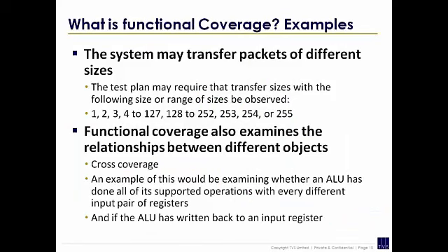So you may have said, actually, what I want to do is see these sizes going to particular addresses. So you get a classic matrix. Maybe you said sizes 1, 2, 3, 4 to 127, etc., and maybe going to addresses 0, address H, address AA, address FF, some addresses. I'm not sure what the important addresses are. Then you can say, right, what I want is that, and I want those as well. I want 0 to all of these, but AA is only going to be important at the top and the bottom. And you can create these matrices by what we would call cross coverage.